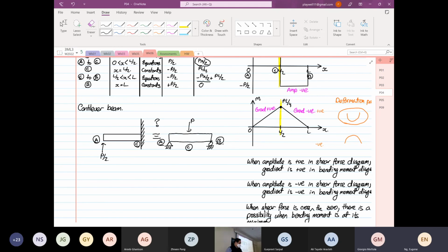So that is your cantilever. Likewise, if it's simply supported and bent this way, we also fail at point C, at the center. So by failure analysis, point C is where failure will occur.